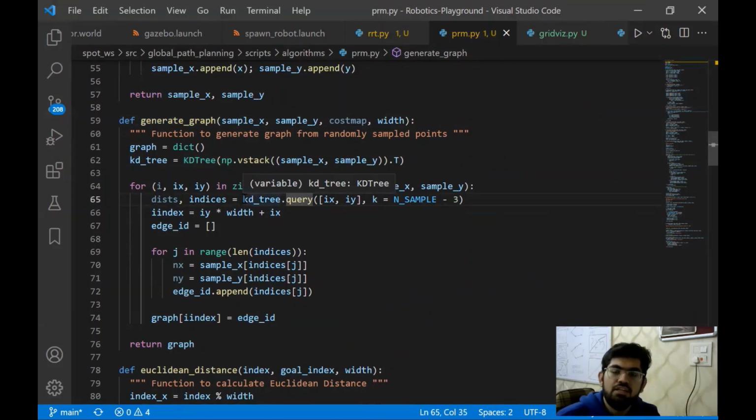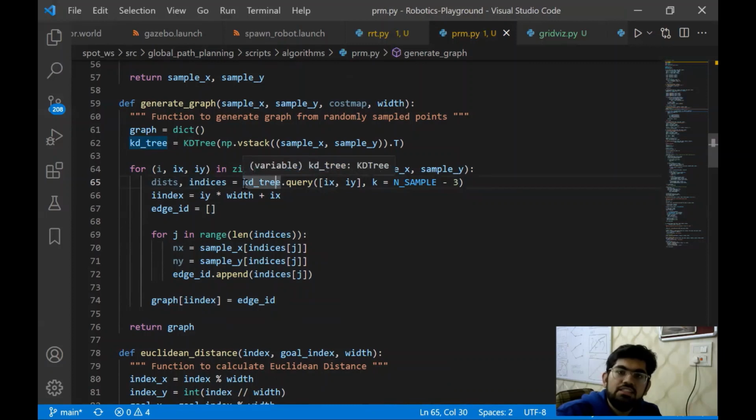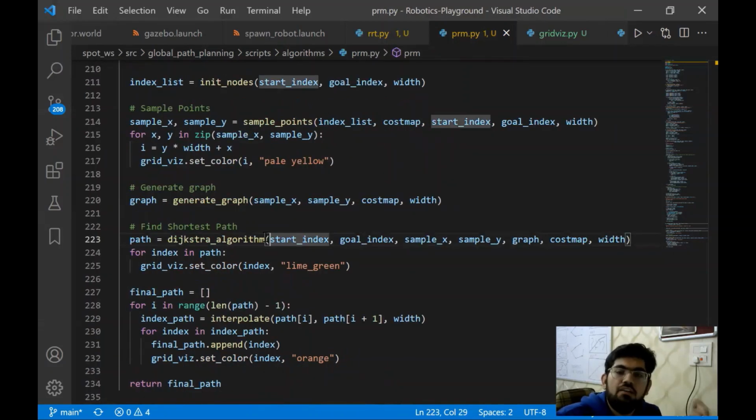For each point, we sample some of its nearest neighbors and connect that point with these neighbors. Doing this connection exercise for each of the points, we get a graph. Since for each iteration, we need to compute many different nearest neighbors, it is beneficial to use KD trees over here.